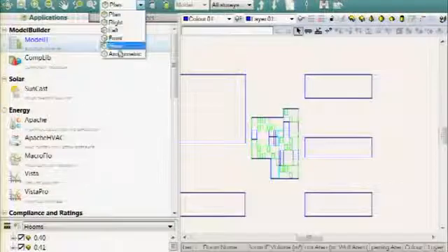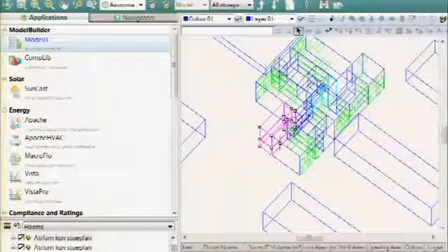Another thing that I will do a lot, as I mentioned to someone earlier: if I have 2 or 3 floors that are working very well, and that third floor is repeated up 100 times in a very tall building, I might just fix those first 3, and then when I go into the VE, I'm going to copy up the rest. So that type of effort, you're getting information from the BIM model, but you're not saying, oh, on floor 72 I have an error, and I'm going to spend 2 days trying to fix that, when I can just focus on the ones that I need to fix, and the ones that are repeated, I copy up.